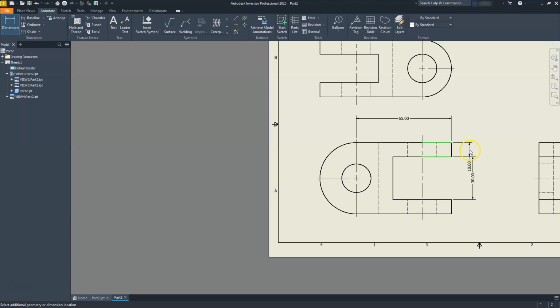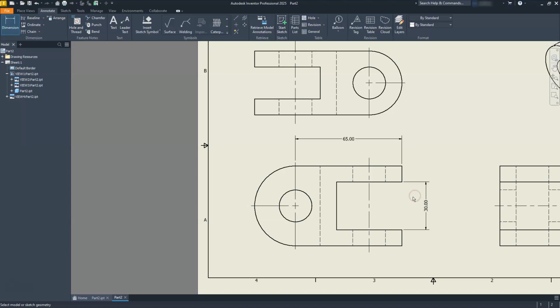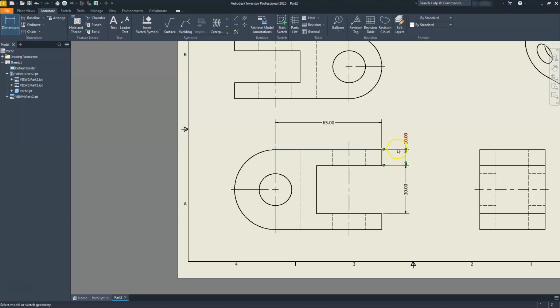And you can see this is one of those first things that I always warn you about, and I was just clicking away on this one. But if you're doing your dimensions, you can see that some of these are going to interfere. Remember with this one, the first place you pick is going to be what side it puts the dimension on. So I wanted that to be at the top, so make it a point to pick that first point at the top.